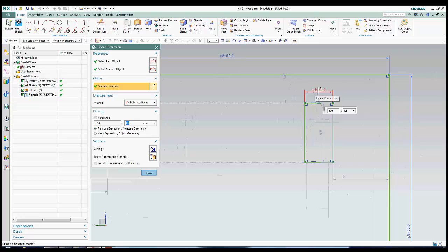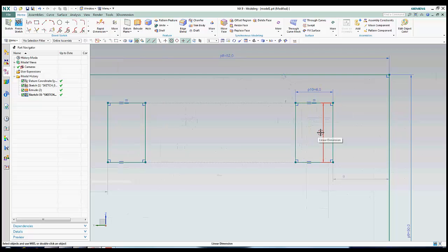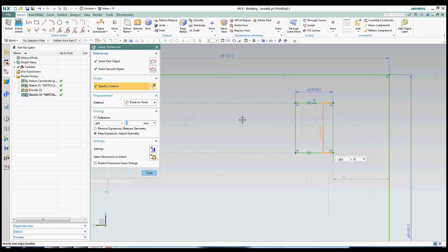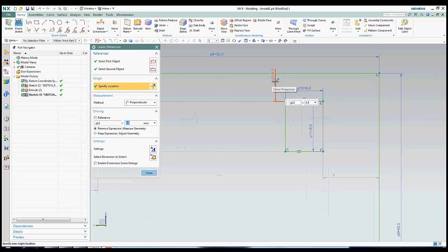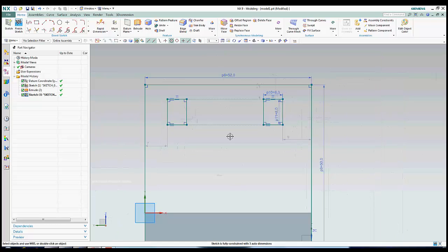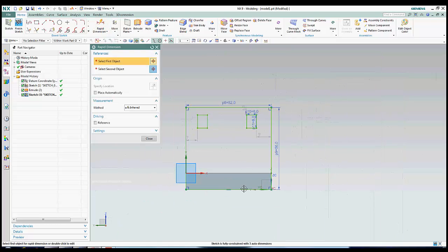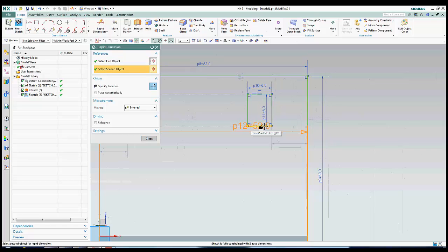As you can see, I can simply select the auto dimensions that I wish to define, double-click them, and then type in the number after they've been placed. The sketch I'm going off of has the dimensions starting from the bottom of the part. As you can see, when I create the dimension from the bottom of the part, the auto dimension that previously covered it disappeared.